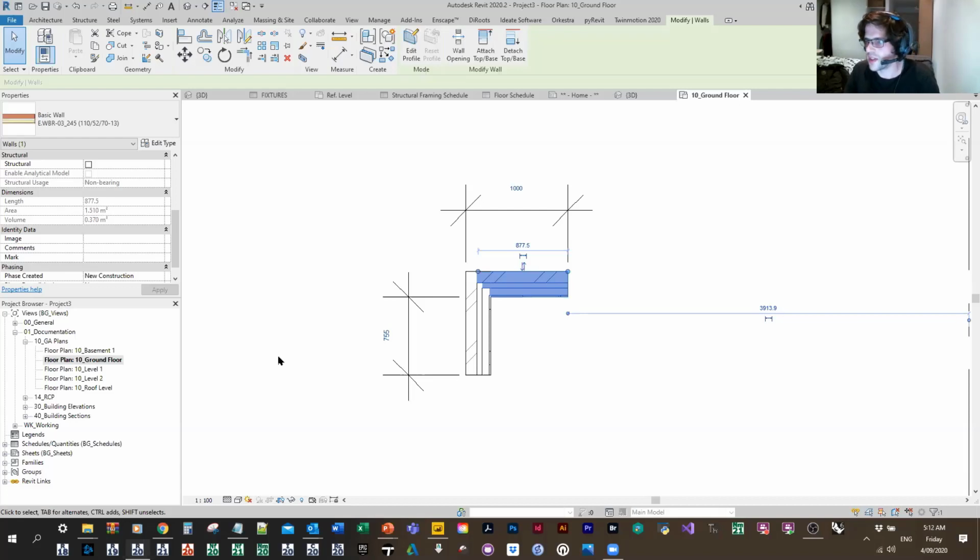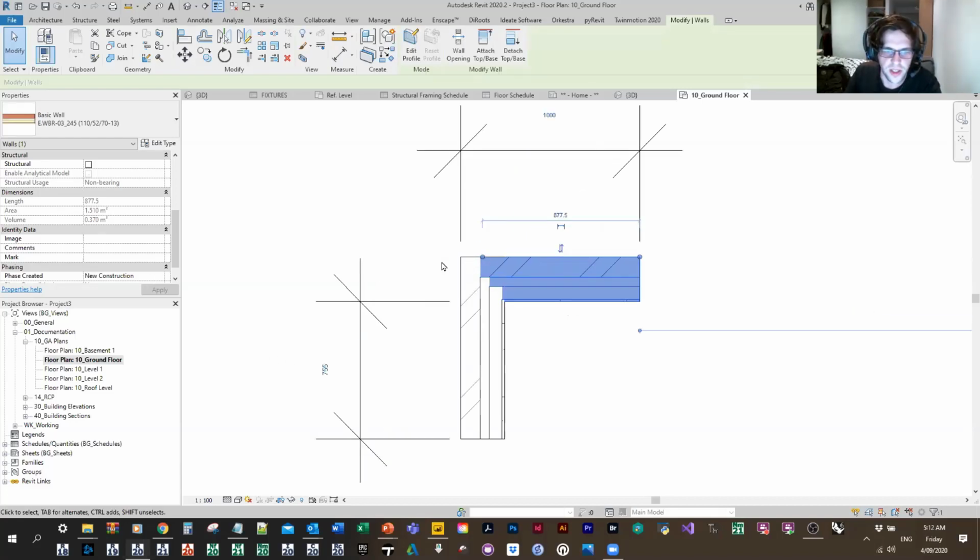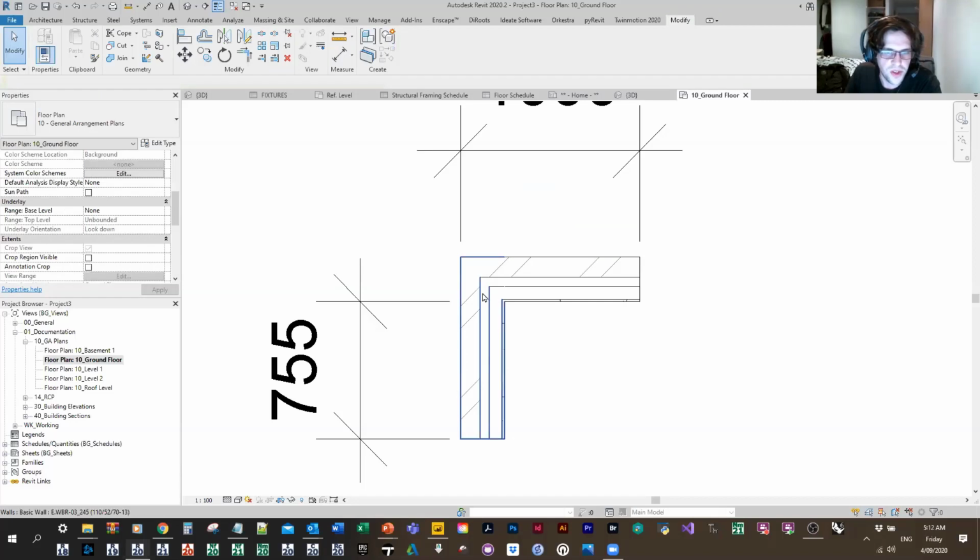And this does work for some types of walls. Like for bricks, it actually makes sense because the brick would typically go out to a corner and then quoin to the next layer. So it's okay to measure it that way in most cases. But sometimes if you're doing things like partitions, it can lead to some little minor discrepancies in how you get the total.